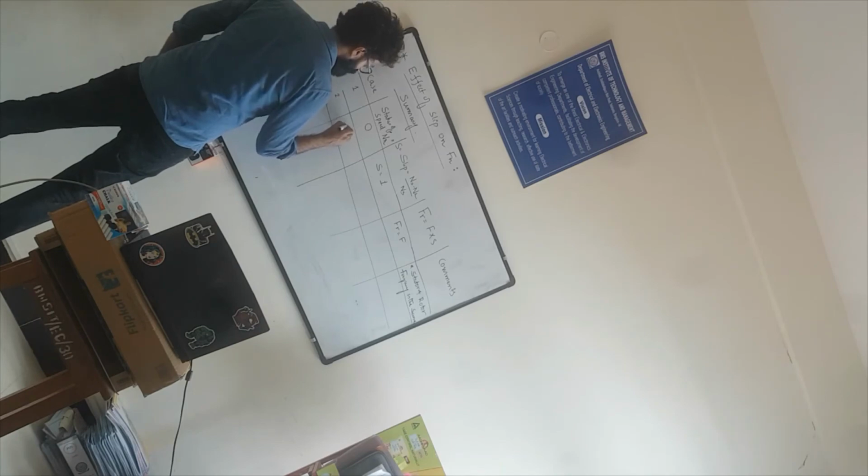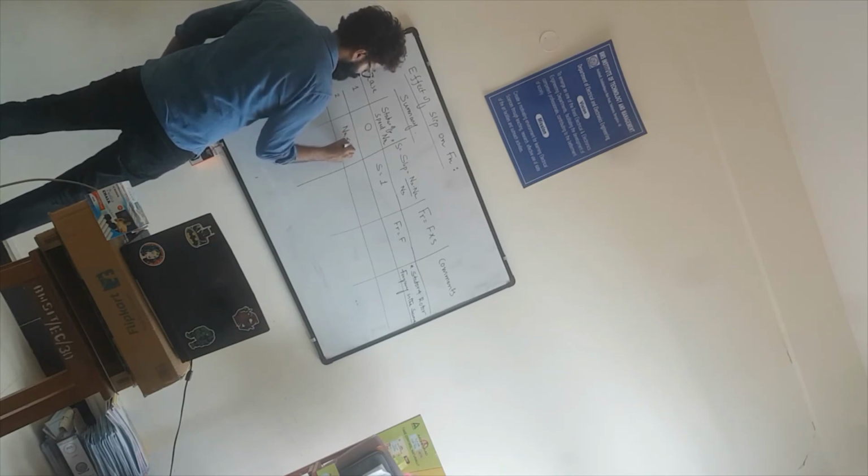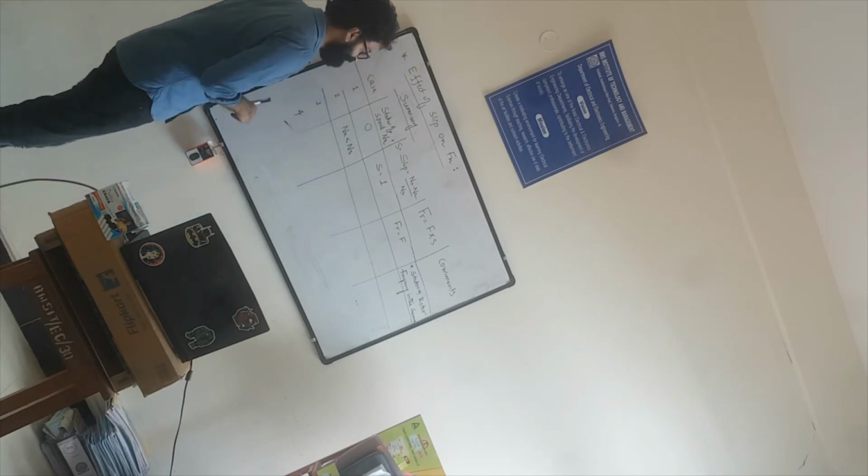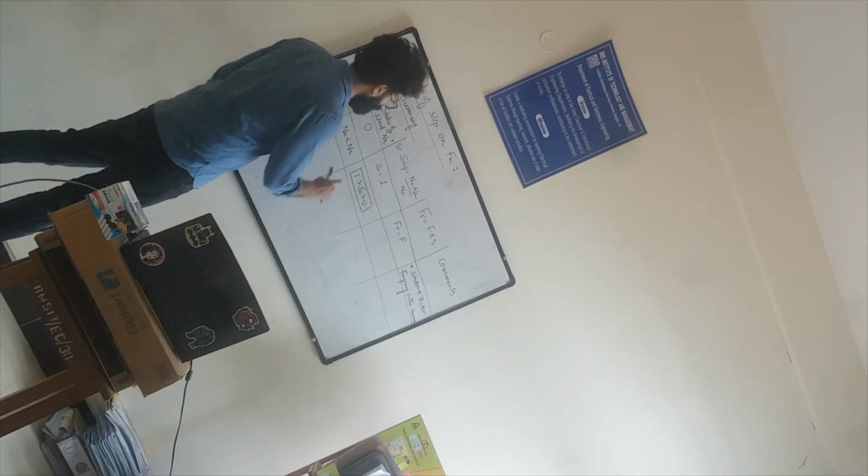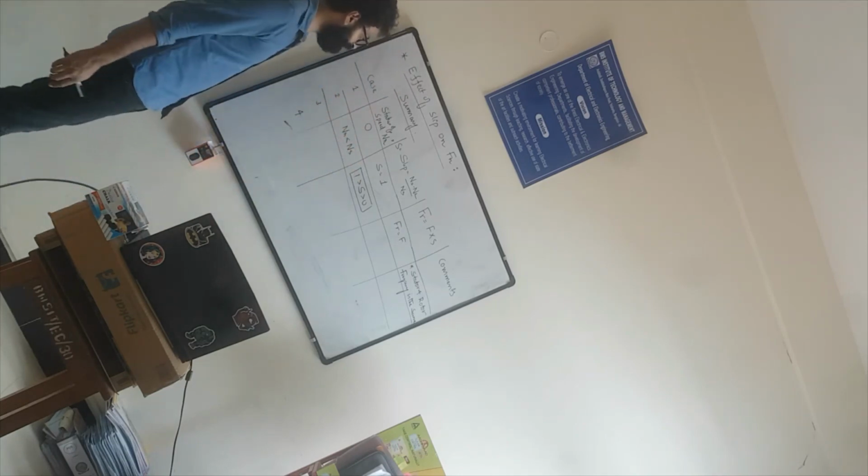Now let us assume that the status of NR is such that NR is less than the synchronous speed. When rotor speed is less than synchronous speed, the slip value is greater than 0 but less than unity, because unity you will get only when NR is equal to 0.